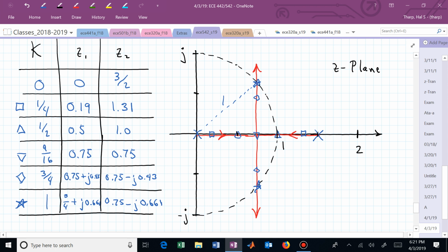So now the question was, does that mean that we know the shape of the root locus? The root locus isn't going to curve any way. In this case, since we have 2 real poles and only 2 real poles, we know that we're going to meet halfway between those 2 poles and then go vertical and not curve at all. We're just going to go straight up and down at plus and minus 90 degrees. So given that, that's what we're using to calculate that point star.